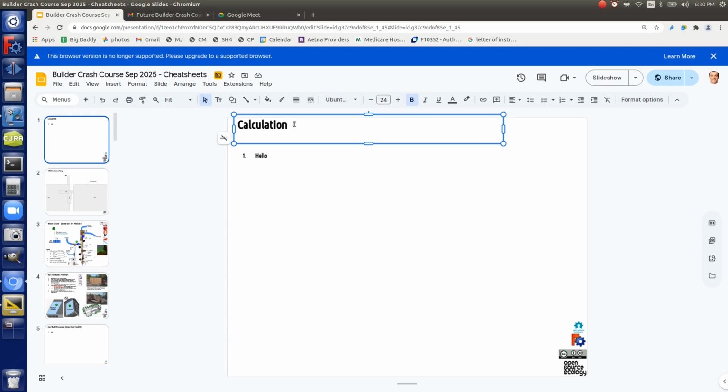But 5 tons, that's a lot. Now, you can only go so high. If you made this 20 feet, that thing is going to start buckling. So now you have to look at the condition where it's so long that it will bend and collapse. It won't crush, it will bend and break. If this was fixed to the brick wall and cannot move, absolutely, 5,000.